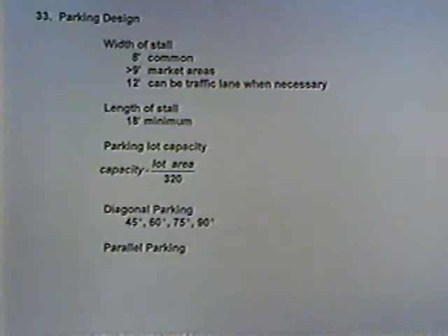The reason they're wider in market areas is so that shoppers can open their car doors and not ding the car beside them. It's easy to get in and out, and they're more likely to come back to that shopping area. You want the wider stalls where you have a traffic lane adjacent to the parking so that people can open their door and not get hit by passing traffic. Stall lengths are typically 18 feet long, which will fit most vehicles.